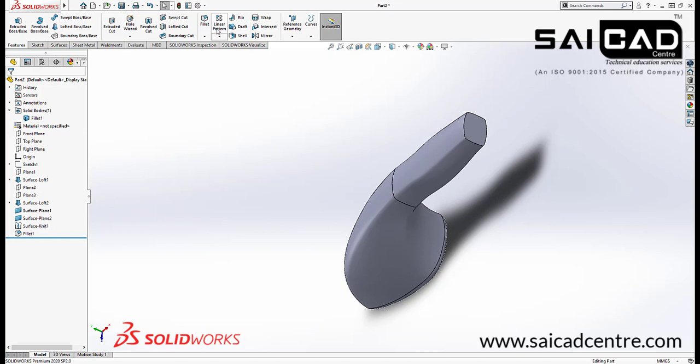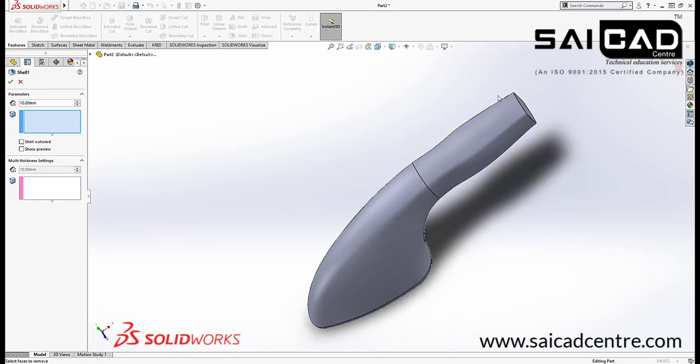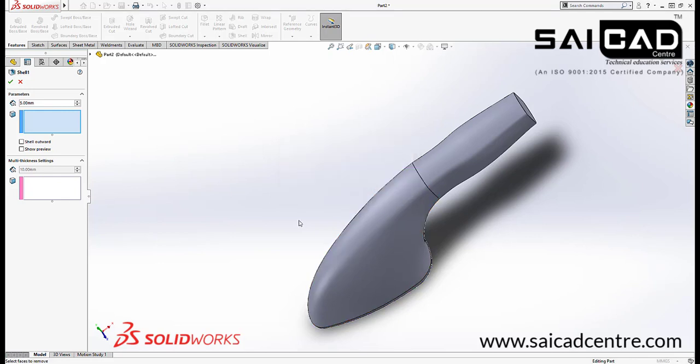Okay, so now next I'm going to hollow it from inside. So go to the shell. I just don't want to remove any part. I need a thickness of 5 mm. Okay, 5 or 2 mm or 3 mm, whichever you need. The thickness value is greater than the minimum radius of the curvature. So you can see that minimum radius of curvature, we need to cut it down to around 2.